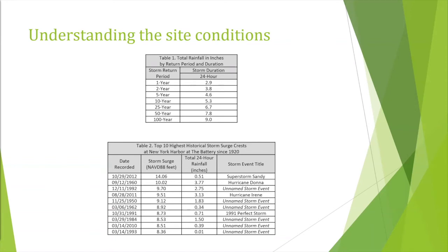Now the storm surge is a different area, and those are two different things, apples and oranges. We really wanted them to understand that so we could find the best fit for their yard. We thought they could use open swales to deal with the rainfall event, the detention that was needed around the perimeter, and a much smaller pump to deal with a 10-year storm.